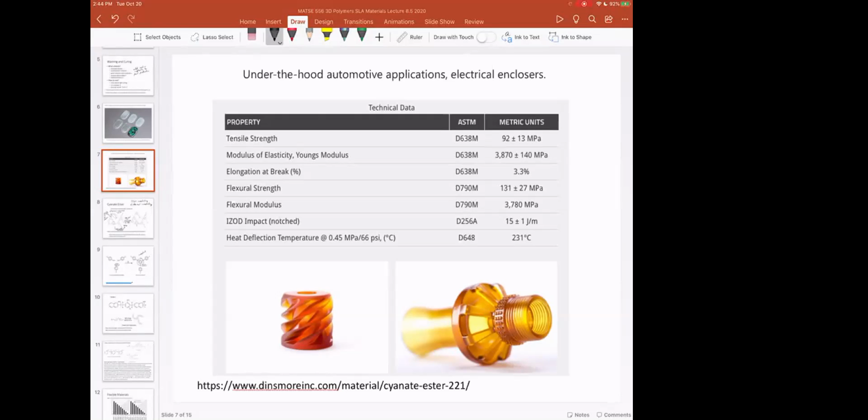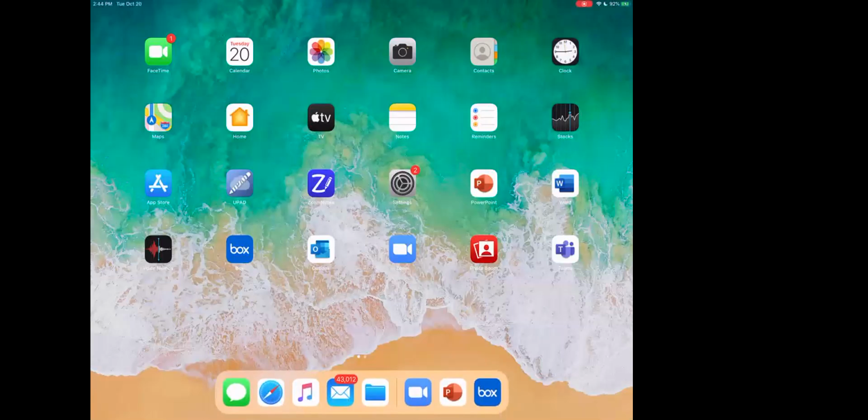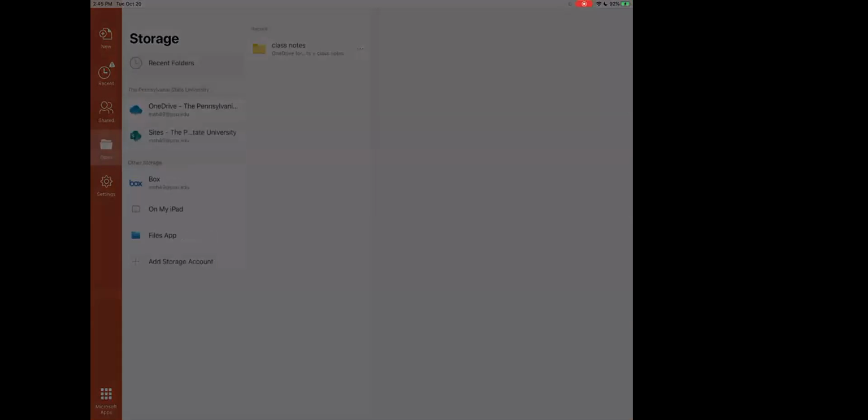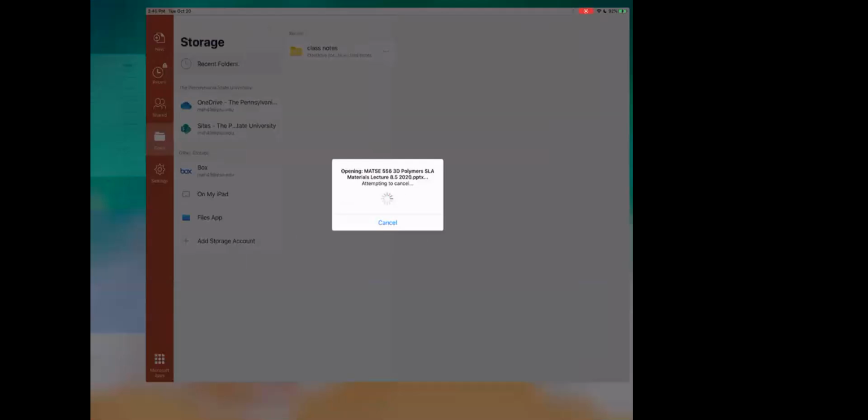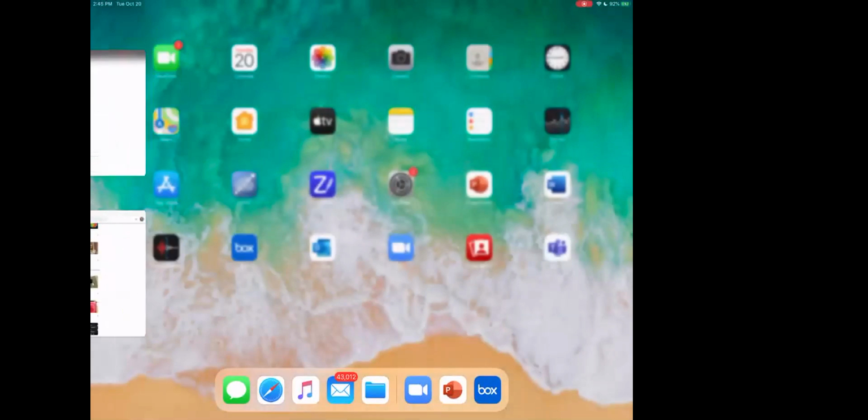And what's interesting is that this is yellow because of that cyanurate linkage. Well, and it looks a lot like Ultem polyimide. It actually has a lot of the same properties as Ultem polyimide. It's just not a thermoplastic. So that's just an interesting aside.